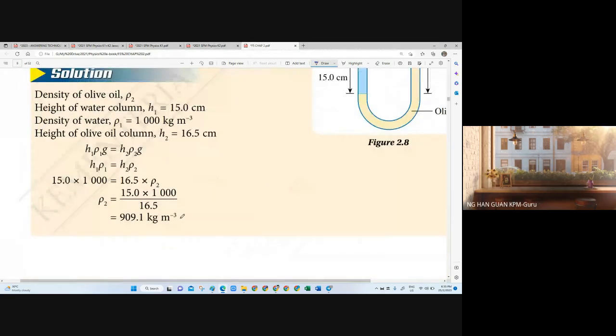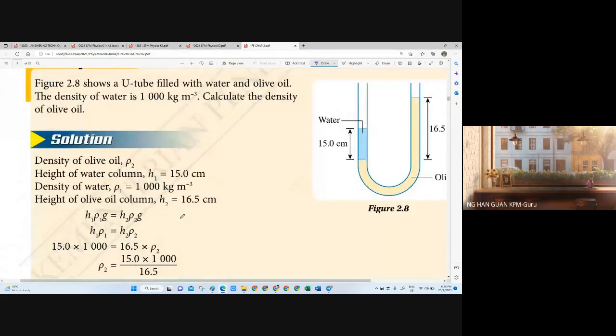Okay, so here's a picture in the liquids about the hydrostatics. So make sure you understand. When the same type of liquid is on the same level, it has the same pressure. But the pressure is calculated from the surface down. At the surface here, this is oil, and on the other side also oil. So at this level, the pressure at this point, let's say I put X here and Y here, the pressure at X and Y is the same.